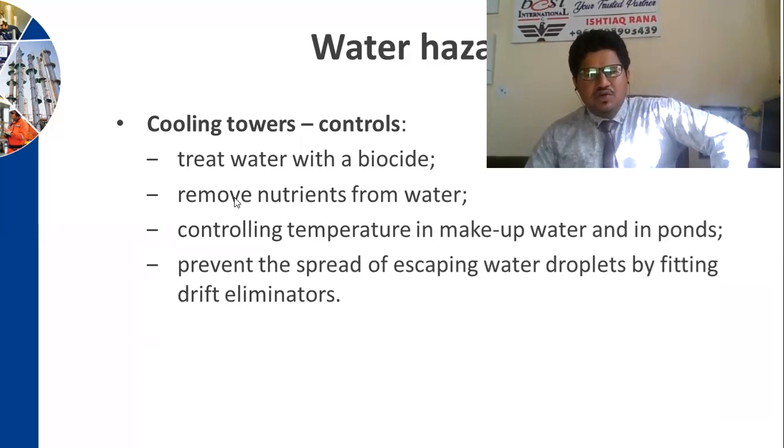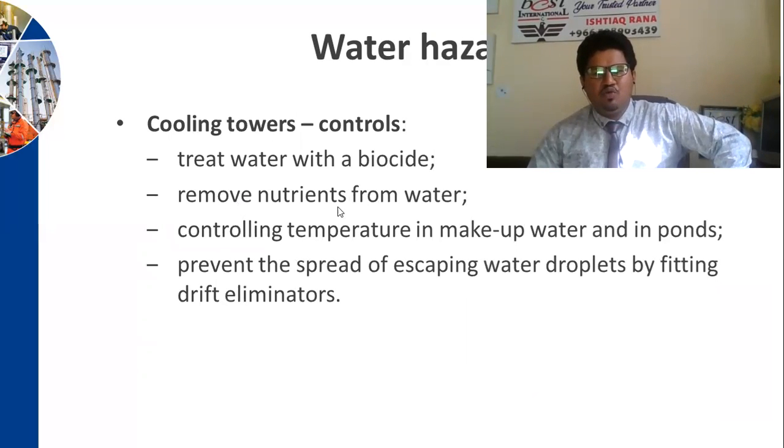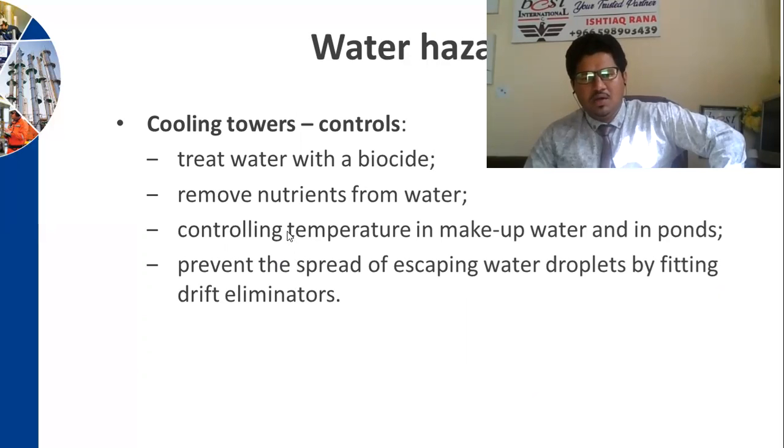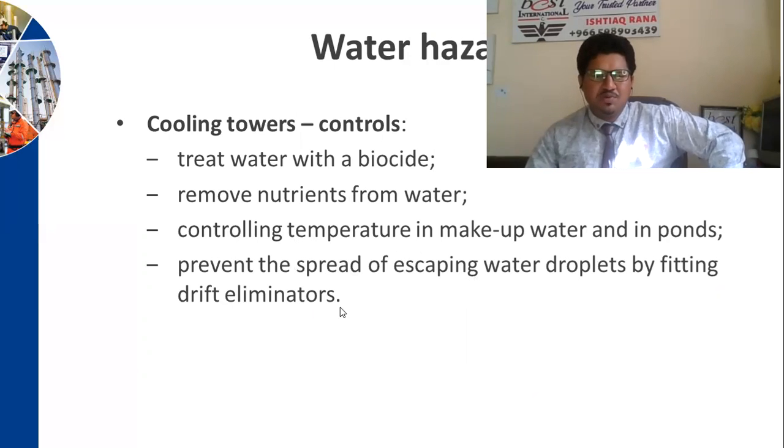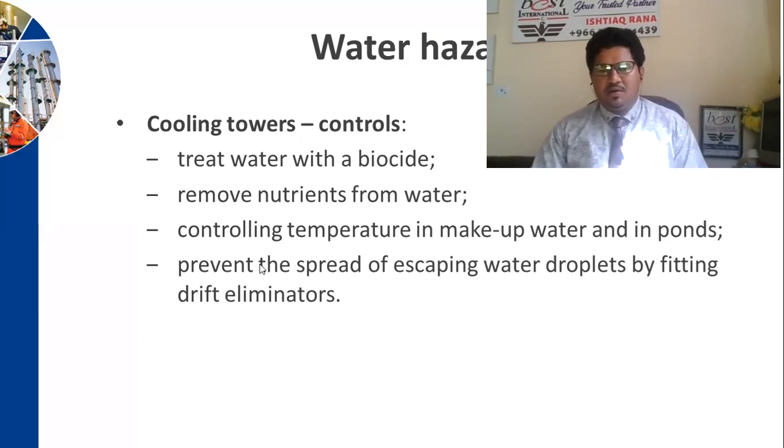Now, cooling tower control is to treat water with a biocide and remove nutrition from the water. Control temperatures of make-up water and in ponds, and prevent the spread of escaping water droplets by fitting drift eliminators.